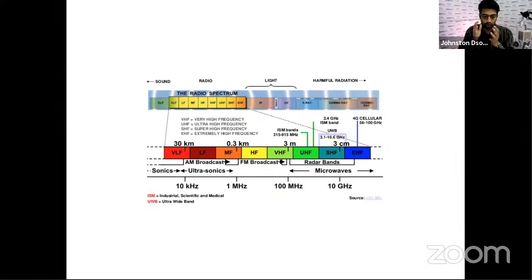If you're going to use your wireless device, say your in-ear monitors or your wireless microphones, in India, and you go to the US and buy it, it may not work here because the frequency ranges might be completely different. And those frequency ranges which are available in the US might not be available in India. They might have been used by some government institution, since mostly governmental institutions use RF. All right. So I'll show you a way of getting to know which frequency bands are free to use.